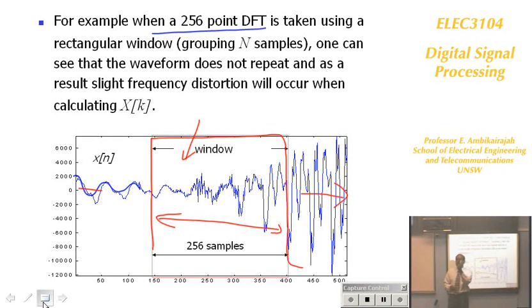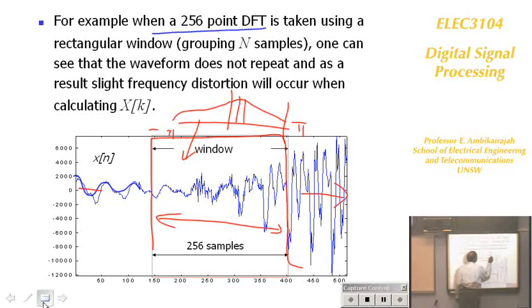And then you find out what is the S0 DC component, what's S1, S2, S3, S4, up to S128. Those frequencies will be repeating on this side because the magnitude spectrum is symmetrical. Pi, minus pi: they are the frequency points you are getting, and they will repeat here.